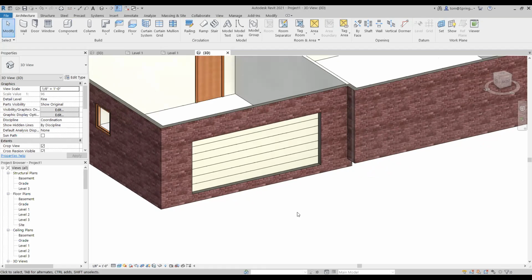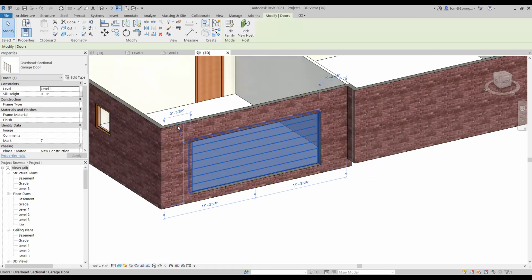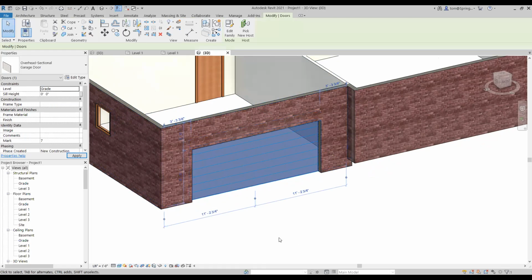It's on the ground level. Yeah, exactly right. So I'm going to go ahead and click on it. When you hover your cursor, if you can't get what you want, you hit your tab key. Like if you're right here, you hit your tab key a couple times until the element comes up that you want. It'll be highlighted when you click on it, and then you can change it. Go into here. So your tab key allows you to do that. So make that gray. Boom.